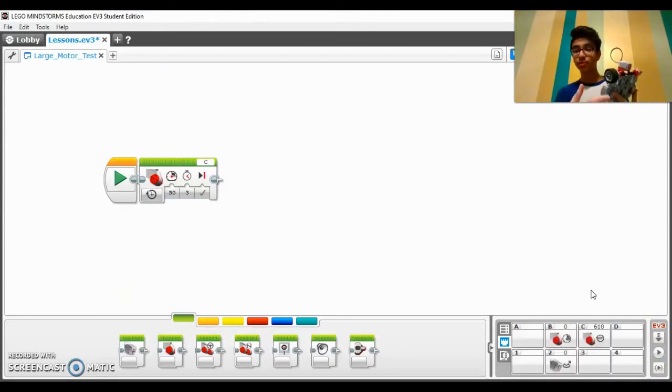So as you can see, I was holding onto that wheel, and if you paid attention to that bottom number over here, it was actually outputting much lower values than 50, because I was stopping the motor from turning. Now, you really shouldn't be doing what I just did, because it does damage your motor, but just be aware of the fact that the number that you put in over here doesn't always correspond to the output you get over here. It always depends on your load.